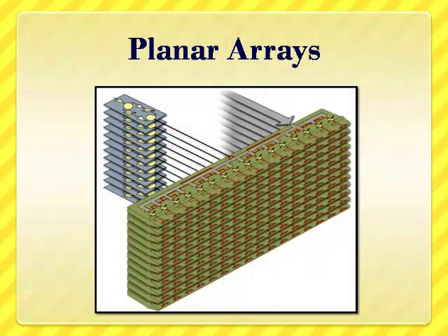In this picture here you can see how we can extend this linear array to a planar array. A set of waveguides will be used to feed the array in a column wise, and row wise each set will act like a simple linear array, and hence you can have a total planar array system as shown in this.